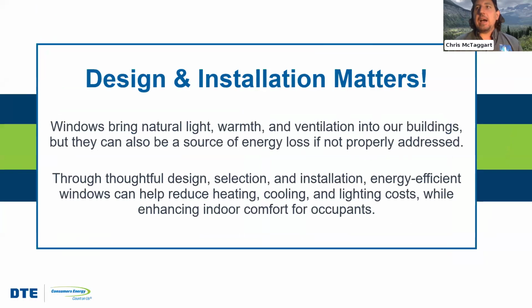So thinking about the design of windows is critical. They can bring in daylight that can provide useful heat in the heating season, as well as potentially useful ventilation for maybe free cooling and just decent air quality if selected and installed properly. So that's what we're trying to get you to, is how can you think about this?